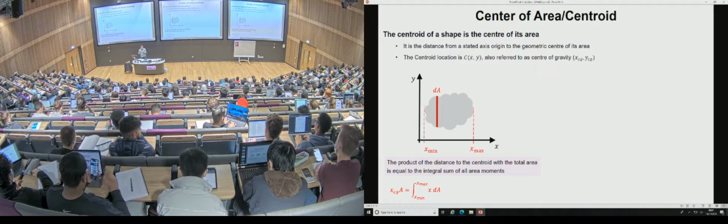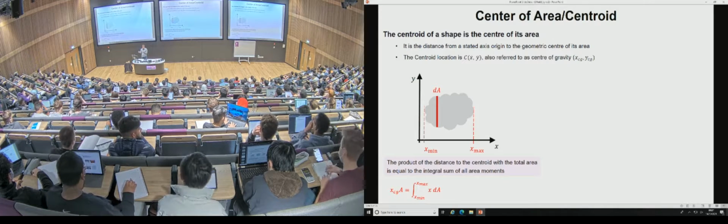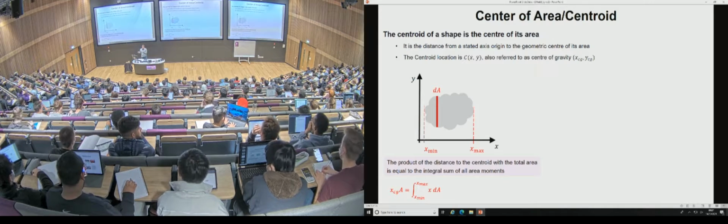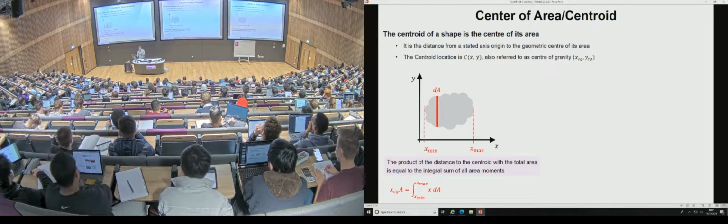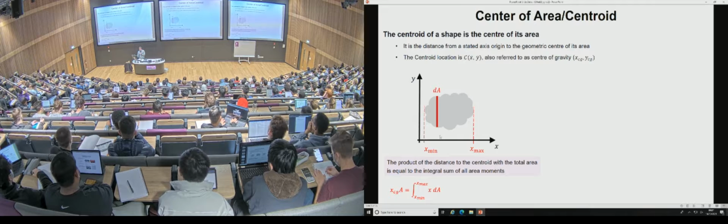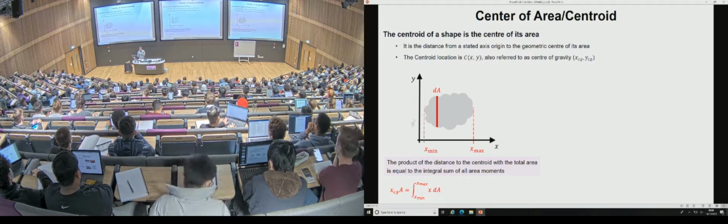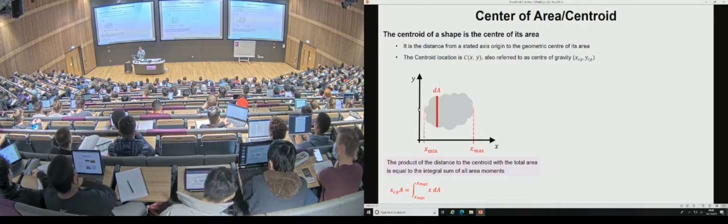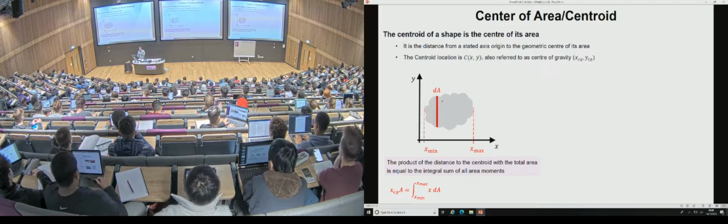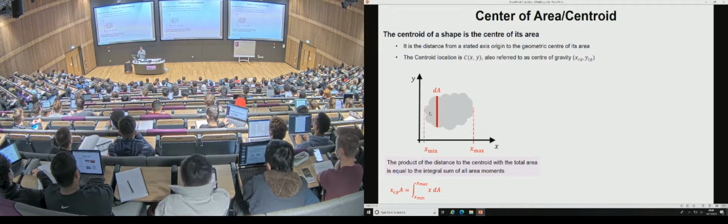But probably you might not have seen it written in this more formal way, where you're doing an integration of an arbitrarily defined shape in grey between its minimum extent and its maximum extent, and you're calculating its moment from the axis of reference, or here, the y-axis, and calculating how much of its mass is located at that location away from that axis.